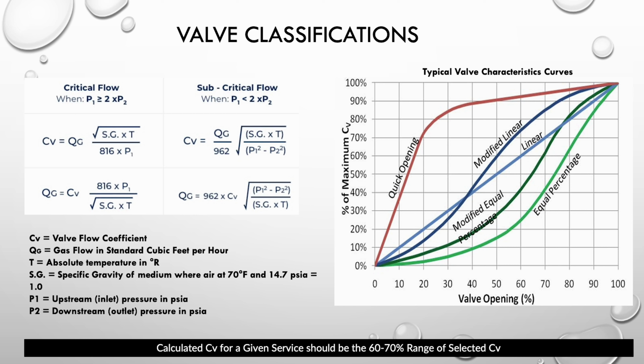It depends on something. And then you have the common type of valve where, if you have a CV at 90%, the opening of that valve at 90% would give you literally 90% of that CV.